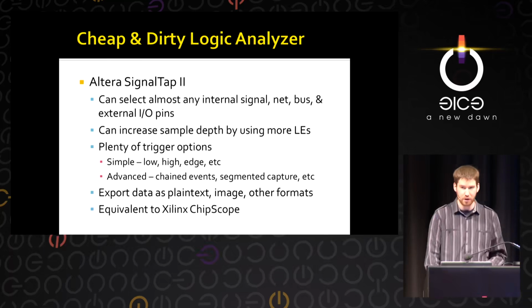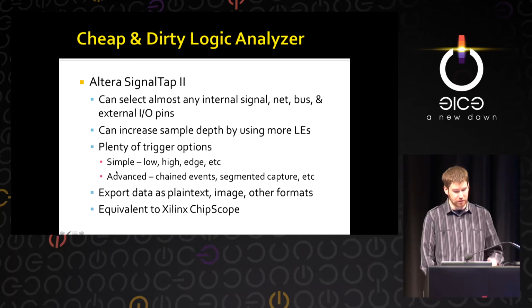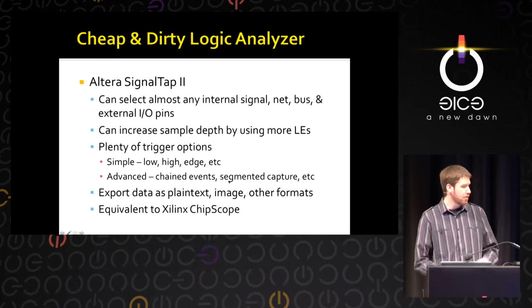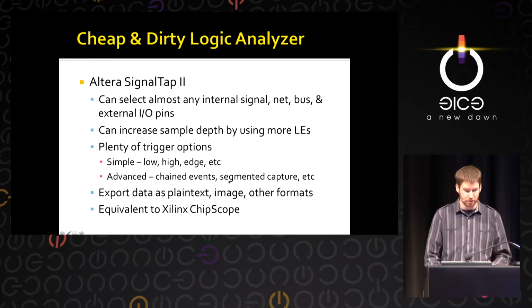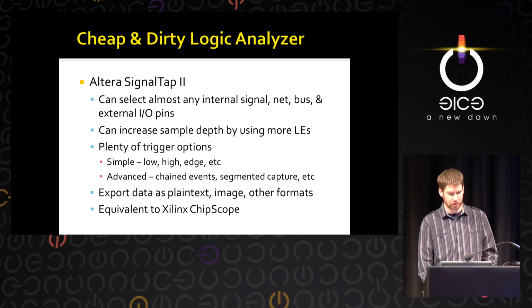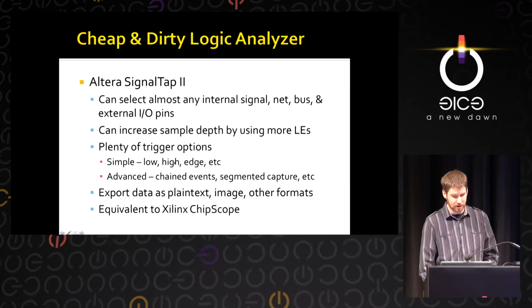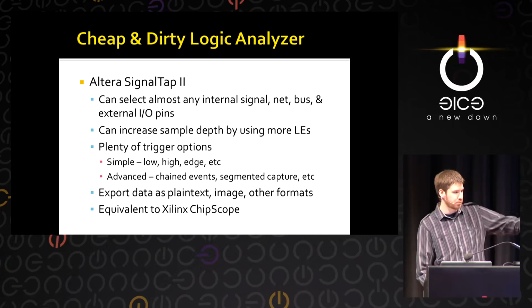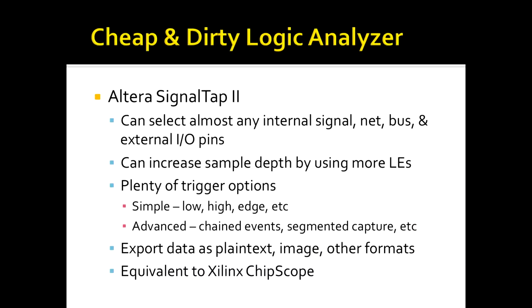So there's plenty of trigger options, from simple low, high, or edge triggering, to where you can chain events and do multiple segments of capture. So it's got all sorts of triggering and storing that a full hardware logic analyzer would have. And then you can export the data in plain text, images, or other formats. The plain text would be a comma separated list of the signals over time, like 1010, and you can parse that back into an actual protocol. So it's equivalent. It's also called Xilinx ChipScope if you're using the Xilinx product.